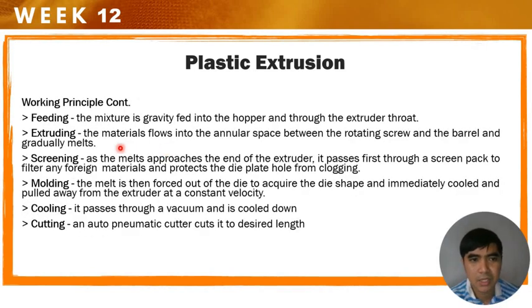So feeding: the mixture is gravity fed into the hopper and through the extruder throat. Extruding: the material flows into the annular space between the rotating screw and barrel and gradually melts. It is the same as injecting the melted plastics.